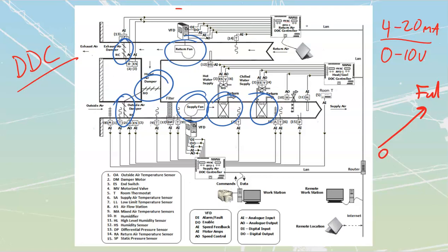Heated water or chilled water is going to be run through there. That chilled water can be chilled through a refrigerant cycle, where we actually just have a heat exchanger with a refrigerant coil that's buried inside a tank, so we can chill down that water. The same with the water can be heated through boilers, etc., but it still just runs through one of these systems over here. This is going to be the most common type of HVAC system that we will have for an overall building.